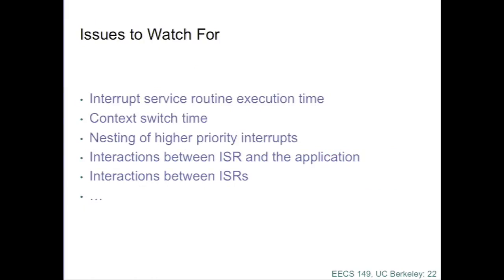Okay, so the issues you need to watch for is, what's the interrupt service routine execution time? In essence, you have to think of it as a pause time. Your program could be paused for an arbitrary amount of time at an arbitrary point, and that makes it difficult to control the timing of that program. If you have an operating system, the interrupt service routine is often a fairly involved thing that's going to execute some context switching policy to decide where it should return from interrupt.